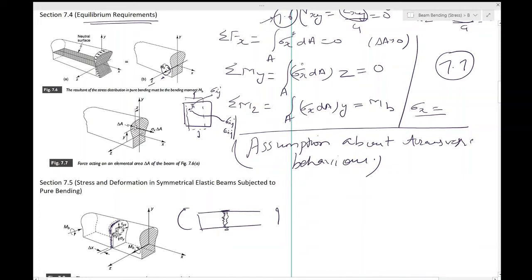Actually, the boundary conditions are always about tractions, which is about the stress vector, but in this case the stress vector and the stress components will be both zero. If you want to check the boundary condition, you can always write that the stress vector is zero, then multiply the stress components with the normal vectors and equate them to zero, and you will come to the same conclusion that it does not have any normal or shear stresses. So this is what we say, that the external surface of this element is free of normal and shear stresses.